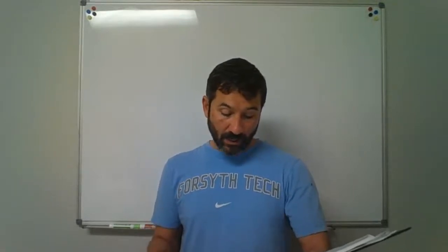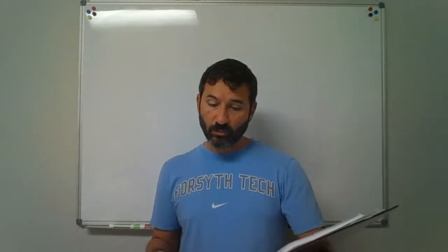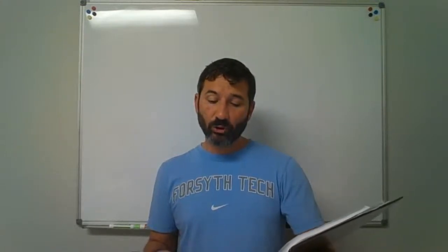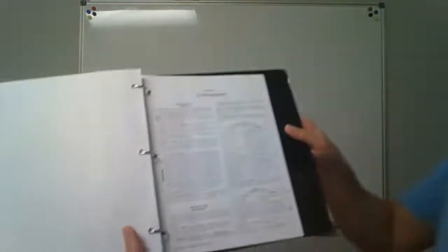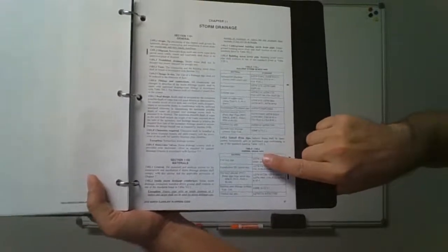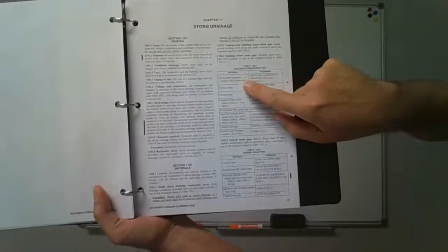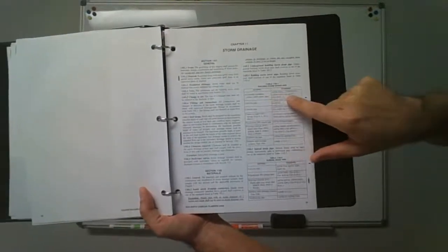Okay, let's look at some building storm sewer pipe. Table 1102.4 gives you different materials right here. So you're looking at those. And then you also have the next table under 1102.5, subsoil drain pipe. And it gives you approved material, ABS, that black plastic piping. Okay. It also gives you some standards.